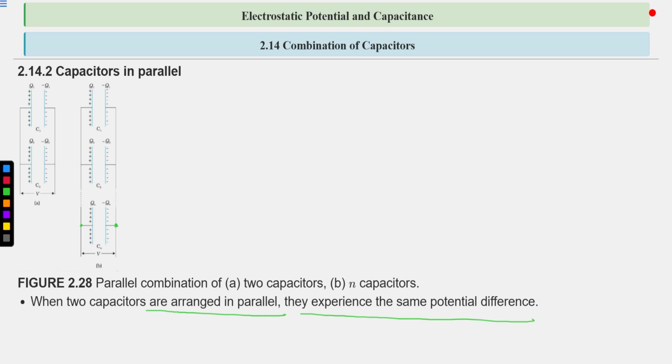So we connect them in a parallel combination. All the capacitors will have a potential difference of 12 volt across them. They will store charge according to their capacitance, and this 12 volt battery will supply the potential difference to all the capacitors. High capacitance will be achieved at very low voltage. So in this condition, parallel combination is used.